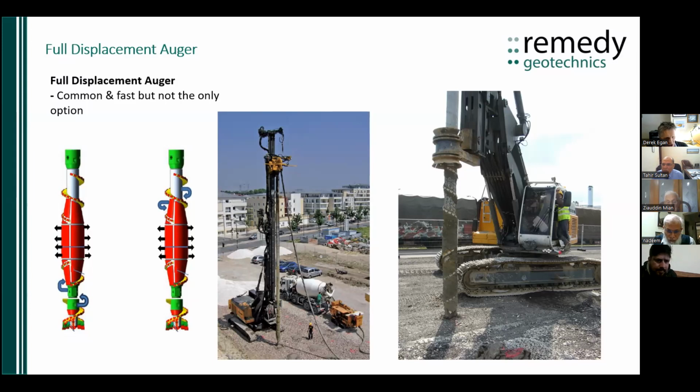So if you could be sure that all the components are working properly, then if you've got excessive settlement, it's probably a design misassessment, and you've probably not allowed for sufficient settlement to occur within the design. And of course, that could be due to a change in ground conditions. You've designed on one ground profile and you've ended up with another one.